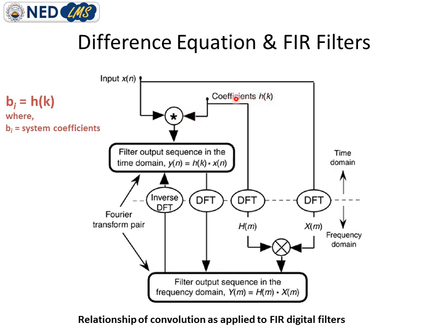We already know the coefficients hk are basically the sequence representing the impulse response, because the impulse response in continuous time is represented by h of t, and the coefficients hk are the discretized version of h of t.